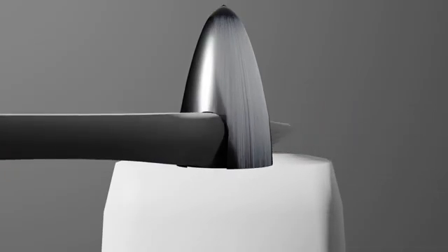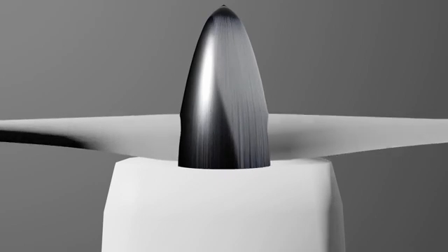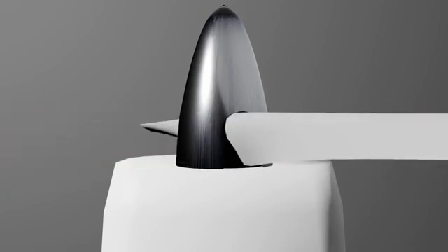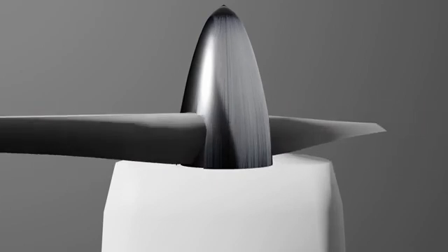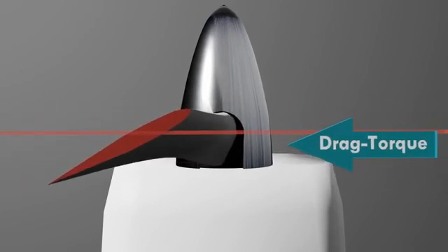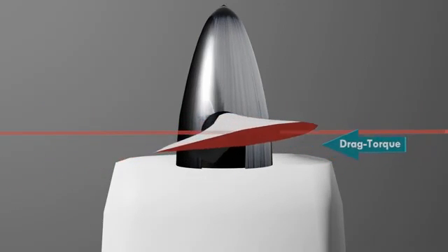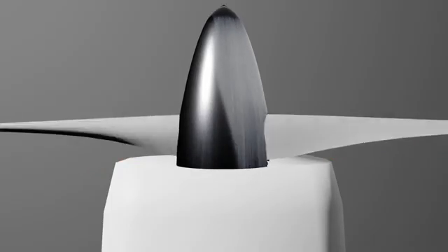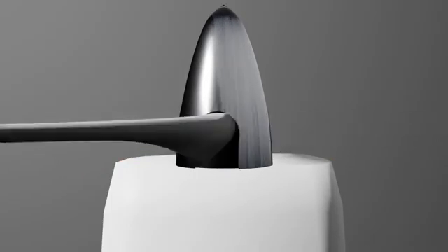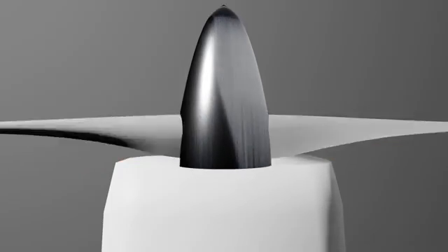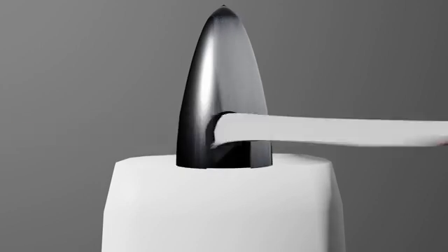Now let's try playing with our new lever, the propeller lever, by moving it forward. This requests a higher RPM from the governor, and the pitch will be decreased, decreasing the blade's induced drag, and the blade spins faster. Note that the engine torque remains the same this entire time. As you'd expect, this is called a fine pitch setting.